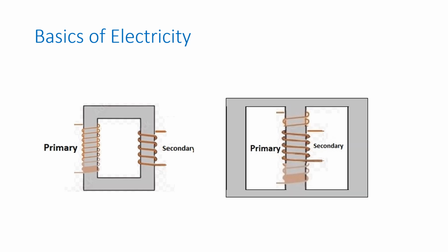Now, the reality is the transformer, if you take one apart, will probably look a lot like this. The windings will be inside of this odd-shaped H core, I call it. The reason for this gets very complicated, but we want to give those magnetic field lines an easy path. So we build it like this, so they stay inside the core, they're concentrated really well, and the transformer efficiency is just really good when you do it this way. So if you get a chance to take a transformer apart, you'll probably find something very close to this on the right.